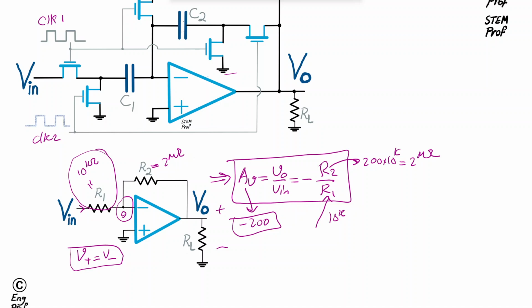Even 10 kilo ohm would require a large area in a chip to realize a meaningful and accurate resistor, let alone the 2 mega ohm, which is completely unacceptable as a passive resistor implemented in a chip, requiring a huge area. These would also come with considerable inaccuracy and variation due to thermal variation and all other parasitic effects, such as the parasitic capacitance of these resistors.